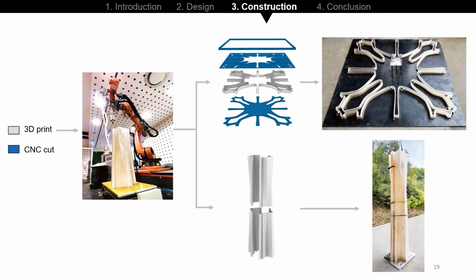The whole column formwork was 3D printed by a KUKA robot with a PETG pellet extruder. A zigzag shape infill was implemented for the formwork shell to enhance strength for casting. To provide extra tensile strength for the concrete, 4 vertical reinforcement bars are prefabricated and installed inside the column formworks. The column formworks were assembled using bolts horizontally and turnbuckles vertically.